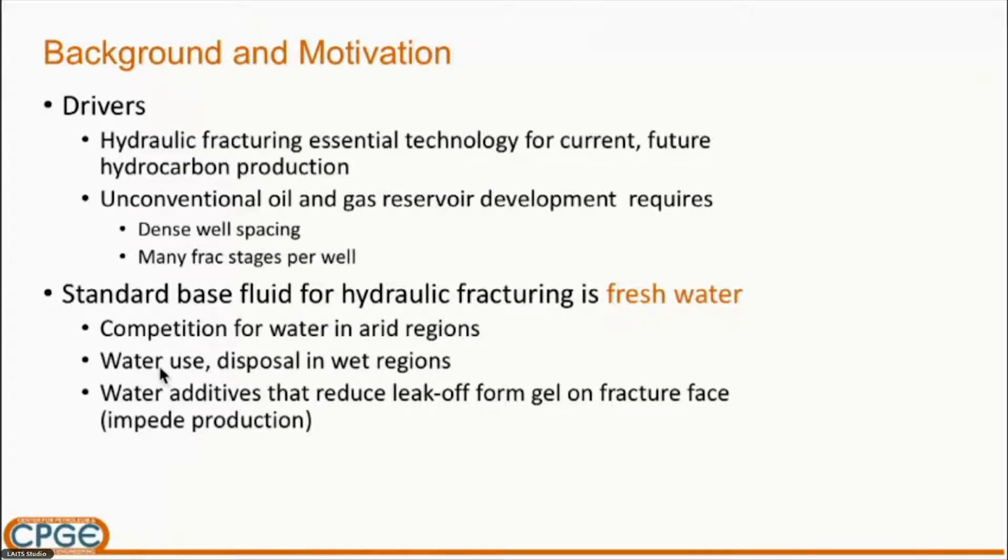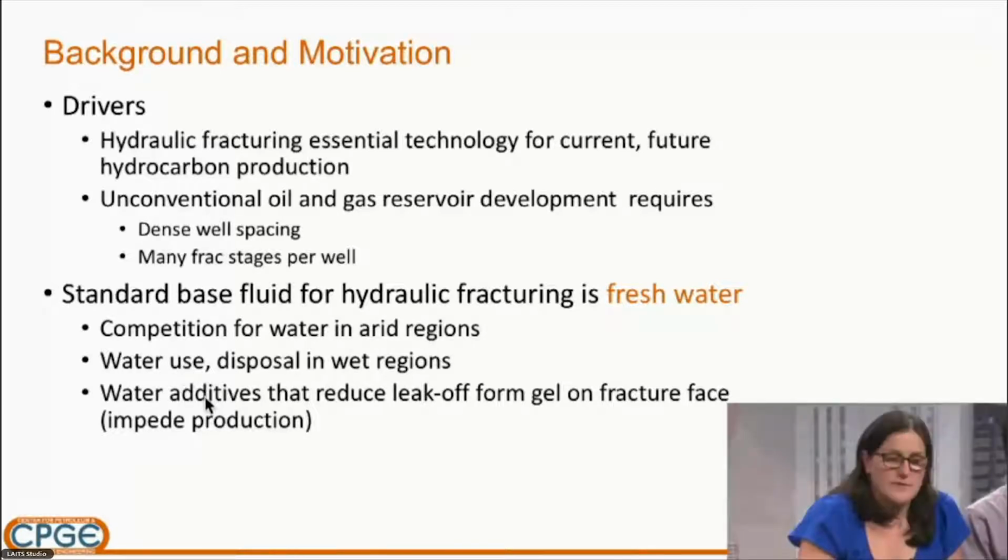And also there's a lot of flowback water that has to be disposed. So regardless of the region you're in, there's a problem of water disposal. And also the extra use of additives that reduce leak off of the water into the formation can impede production later on.